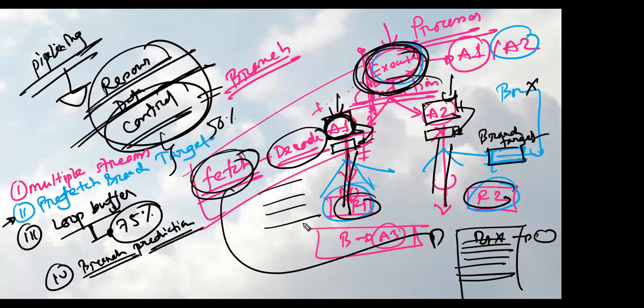Okay, you will jump to the next instruction, jump to the new address or not, or you will perform sequentially. You will execute all the instructions sequentially. There are two ways you could follow. If there is any branch instruction, for example, branch X, you will follow this instruction to jump to the new address. Or if it is false, then you will execute sequentially. That means you are following PC content.